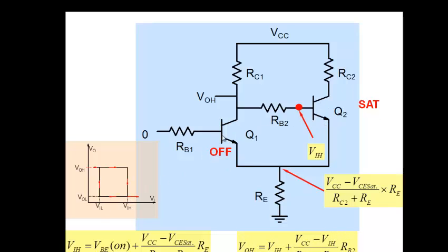All right, so I've already told you the value VIH at which your transistor Q1 turns on and Q2 turns off. So that's the VIH expression over here. And once we know VIH here, this is VIH also, because VIH, if you note, is this voltage plus the 0.7 volt here, which is the same thing as this voltage plus 0.7 volt here. So this point is also, when transistor Q2 is on, at a value close to VIH here.